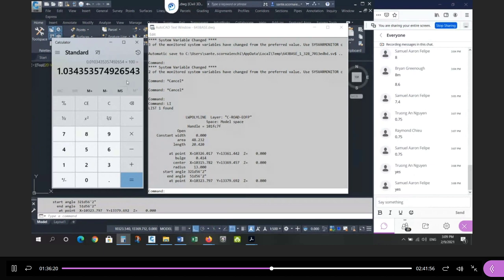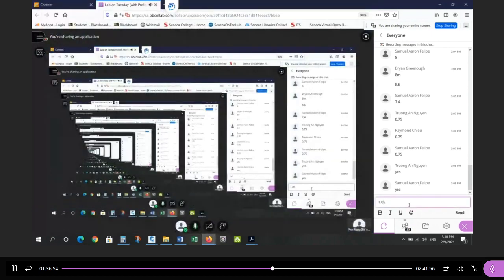Now, I don't want my design to be this number here. It's huge, right? This is kind of a weird number to work with. So now I'm going to round this up, which makes the gutter steeper than 0.75. So then I satisfy the minimum without using a really weird or non-standard value for the center line. Okay, so if I want to round this up and keep it as low as possible, remember I'm trying to achieve minimum slope everywhere, I'm going to round it to 1.05 or 1.1. Okay, so I'm going to use either 1.05 or 1.1%, okay?